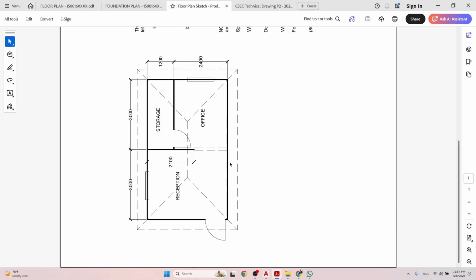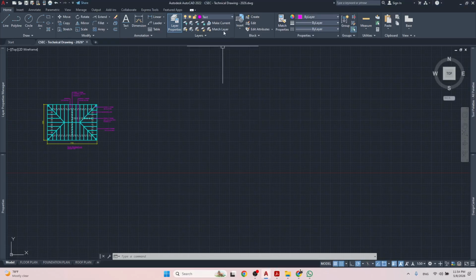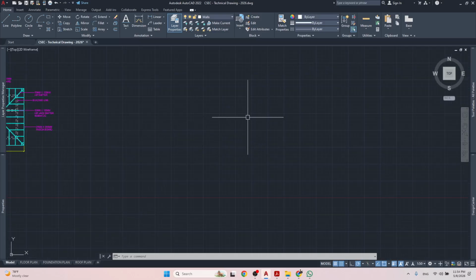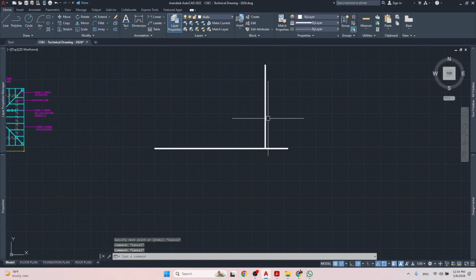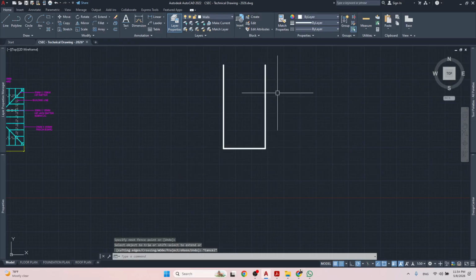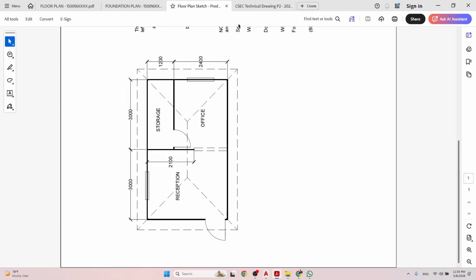the door. Okay. So let me go to the wall layer. We're gonna draw it right here. So let's start with the concrete slab on the floor. I'm just drawing a line, and then I'm going to put a line going up like this, and then offset 4050. Okay, so let me just trim these off.